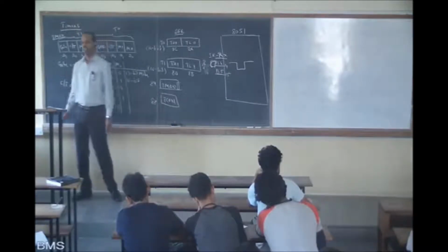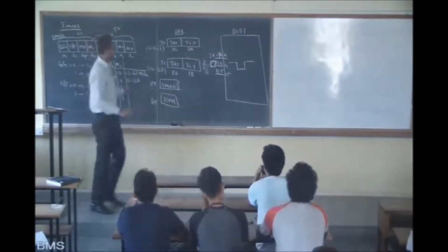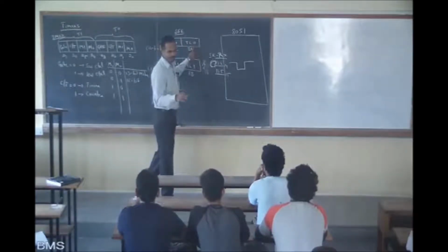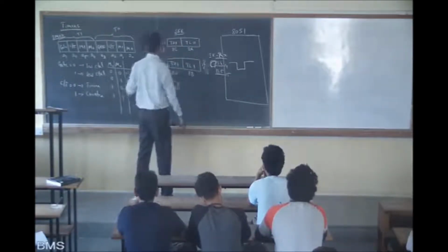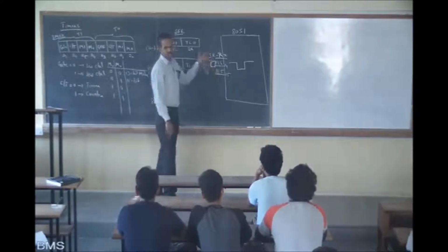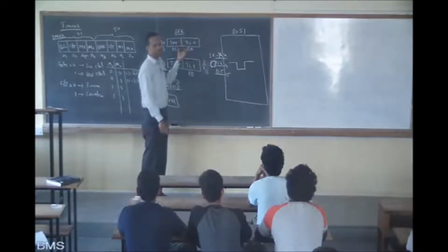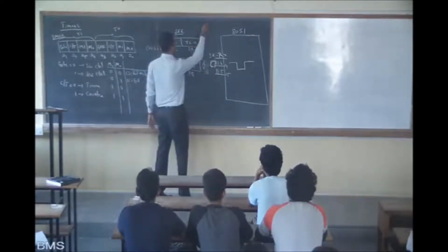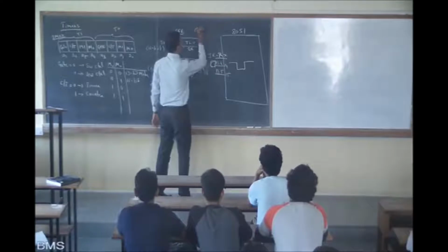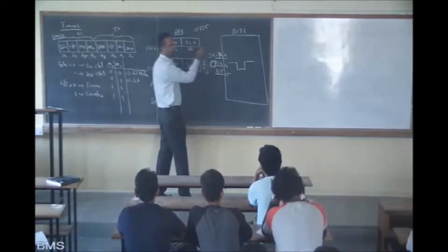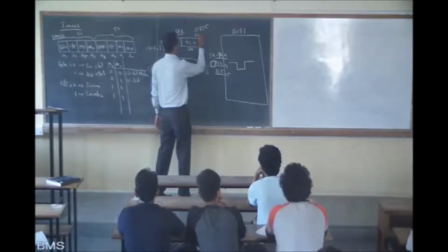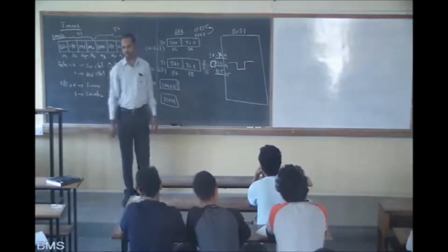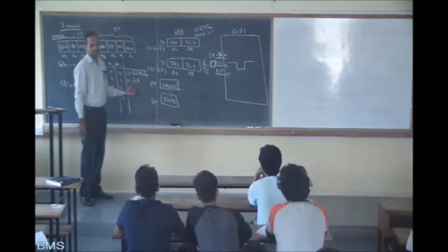Mode 1 is the 16-bit mode. This is a normal 16-bit register. Put 0000 here, give a clock pulse from the clock frequency or from the counter, and it starts counting. The maximum value it counts is 65,535, which is FFFF. It will not be in decimal, it will be in hexadecimal, so you should convert that. This is the maximum number it can count for 16-bit.